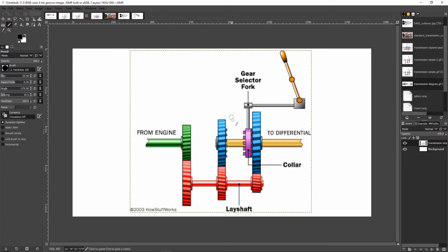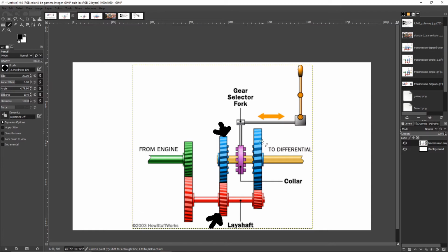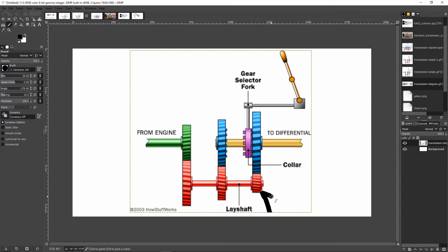So here the gear selector has now splined with these and is engaging this output shaft to this gear selection. Before, on this picture, this gear and this gear and this gear were all rotating together, but nobody was actually tied to this output shaft, right? But here, we're going to engage what I'm calling second gear on this gear set. Now the output shaft is splined to this gear set, and I'm going to achieve my gear ratio of whatever second gear is.